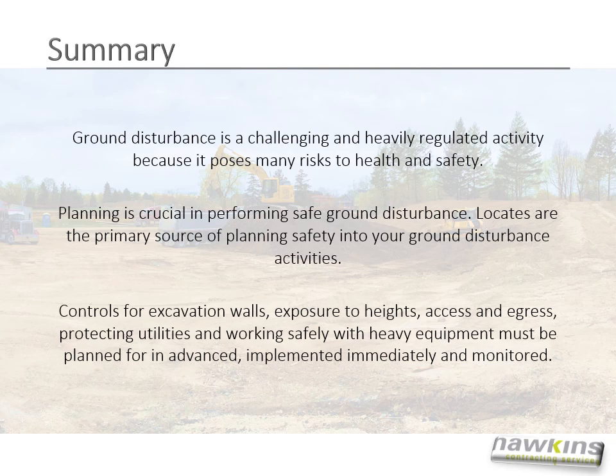In summary, ground disturbance is a challenging and heavily regulated activity because it poses many risks to health and safety. Planning is crucial in performing safe ground disturbance. Locates are the primary source of planning safety into your ground disturbance activities. Controls for excavation walls, exposure to heights, access and egress, protecting utilities, and working safely with heavy equipment must be planned for in advance, implemented immediately, and monitored.